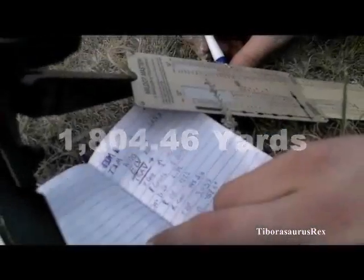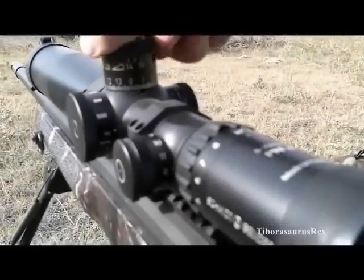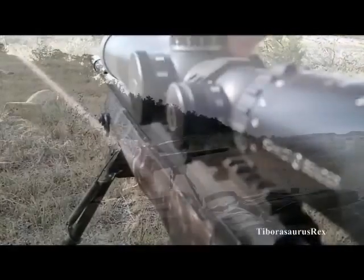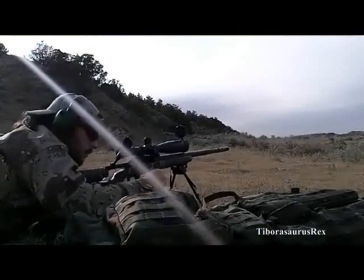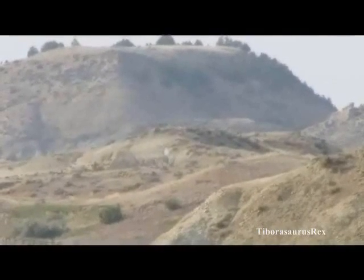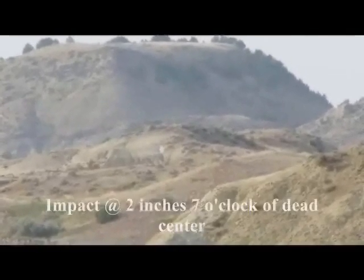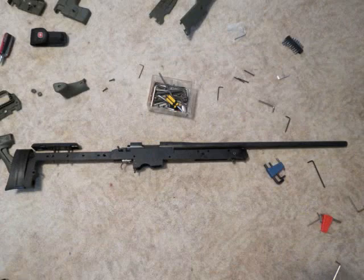The best way to take care of that is just by free floating. You're going to want to make sure you don't have any stock warp issues. And that can also have an effect on the bedding of the rifle too, especially some of the problems with the injection molded or wood stocks is compression of the individual cells over time, or the compression of the material. And that can cause things to loosen up as well. So you've got to go through it constantly and check your screws. Some guys solve this problem by aluminum bedding. And that's where some of your chassis systems are real popular.